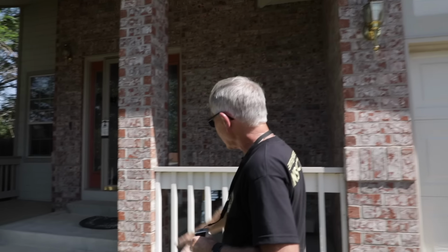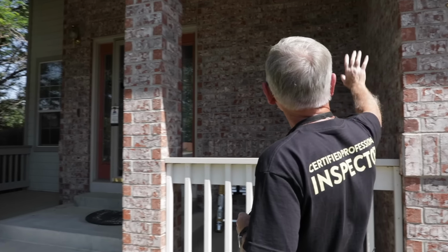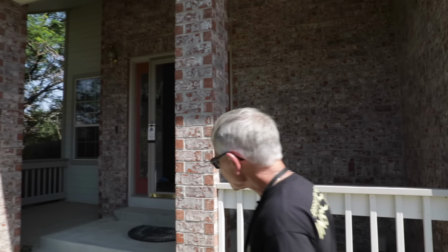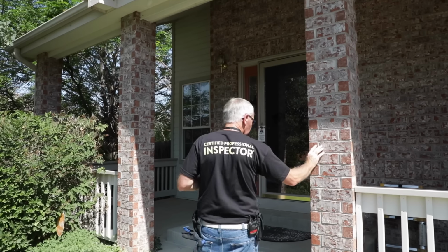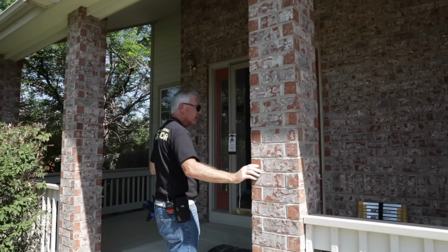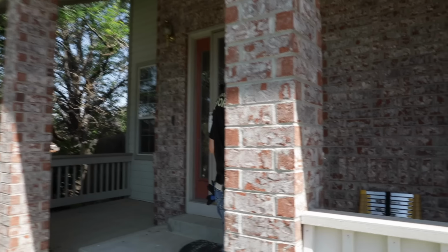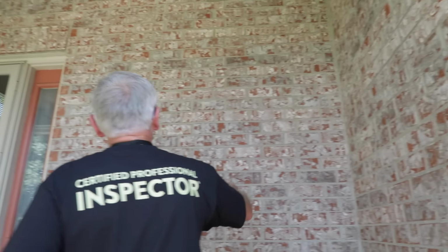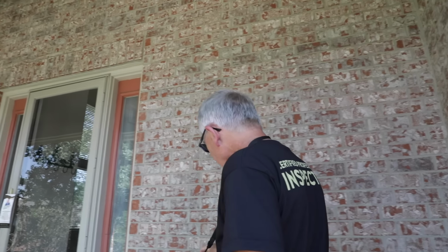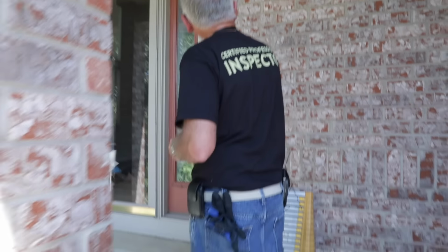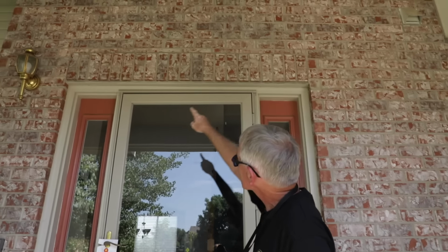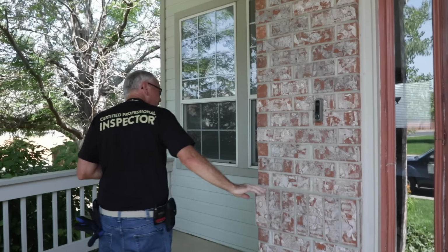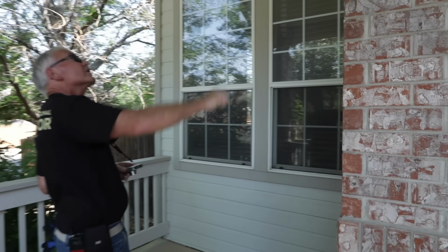And get a little bit over here, we got some brick. We got some brick on the back of the porch here. Got some brick columns here. The brick columns are going to fall under our structural portion, so I'll get that later. But what I want to do is just come in here and look at the brick surface coverings. Look for cracks, any loose brick. Make sure you got your lintel across the door here to carry the weight of the upper brick. And so far everything looks pretty tight, pretty good.